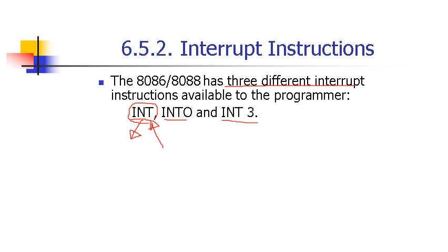We call it ISR 50, and you placed the address of this specific subroutine into your memory, and you have to call the vector inside your memory, which is the 50th vector, to go to this ISR 50 and start executing it. So you can call this by typing in your code INT 50. So you have to follow INT by a number.